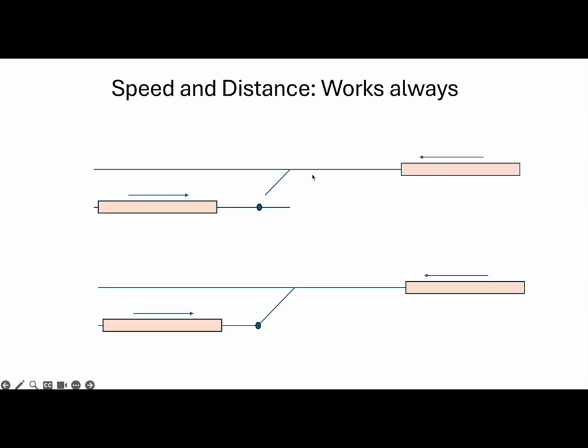So we have what we called in former times a flank protection situation, but here we just have much simpler rules, because for this train, and also for this train, if he wants to prolong his MA so he gets nearer to the other one, we just check: is there any reachable route where he can create a risk or not? If not, then he can use the track speed, which is the physical speed of the track. If the point is closed in a way that they can reach each other, then they are a danger for each other. And now in this situation, prolonging an MA means that speed and distance need to follow a safe function, which means they have a relationship to each other.